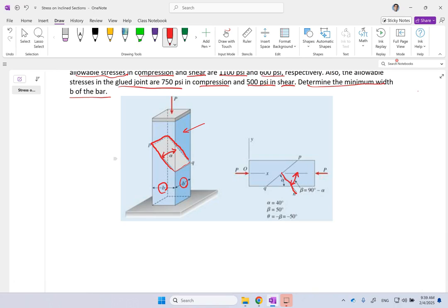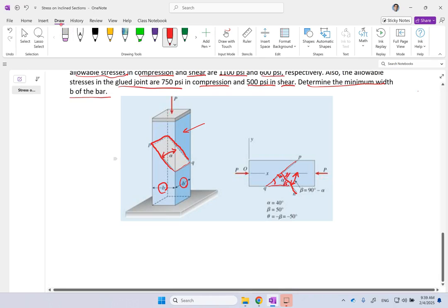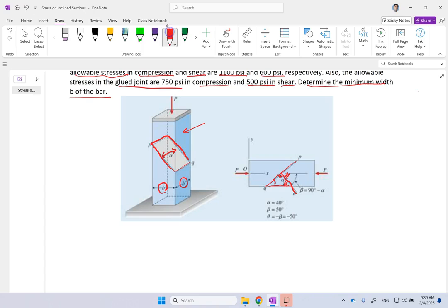Now remember, what angle was alpha? Alpha was the angle of the plane with respect to the vertical direction. So this is alpha, not this one. If this is alpha and this is 90 degrees, this is 90 minus alpha, and that is the same as this angle that you're interested in. So clearly the theta that you have to plug into your formula is this one here.